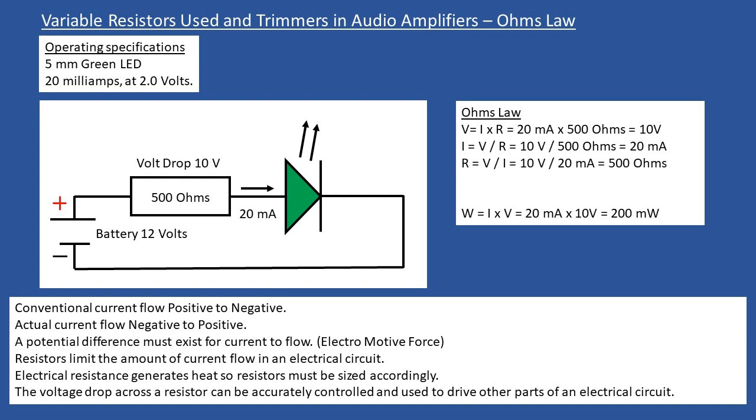So what would happen then is it would drop the remaining 4 volts across that last resistor, and now there is no longer a potential difference. So the current flow stops. And that's the best way I would ask you to look at that, okay? And we see this. If a resistor goes open circuit, then there can no longer be any current flow because there is no longer a potential difference.